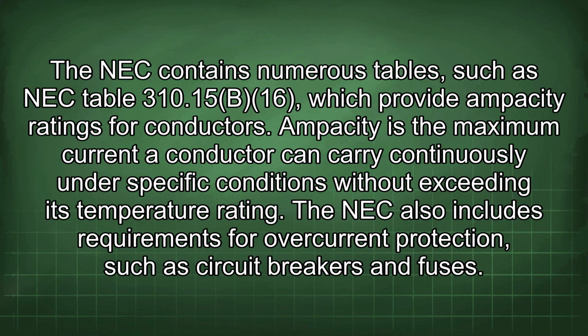The NEC contains numerous tables, such as NEC Table 310.15(B)(16), which provide ampacity ratings for conductors. Ampacity is the maximum current a conductor can carry continuously under specific conditions without exceeding its temperature rating. The NEC also includes requirements for overcurrent protection, such as circuit breakers and fuses.